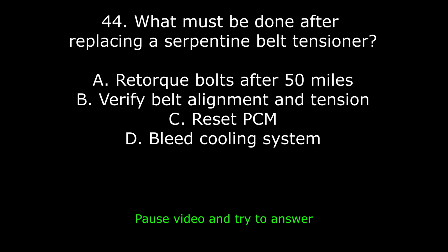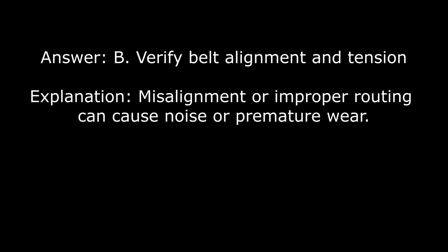44. What must be done after replacing a serpentine belt tensioner? A. Retorque bolts after 50 miles. B. Verify belt alignment and tension. C. Reset PCM. D. Bleed cooling system. Answer: B. Verify belt alignment and tension. Explanation: misalignment or improper routing can cause noise or premature wear.